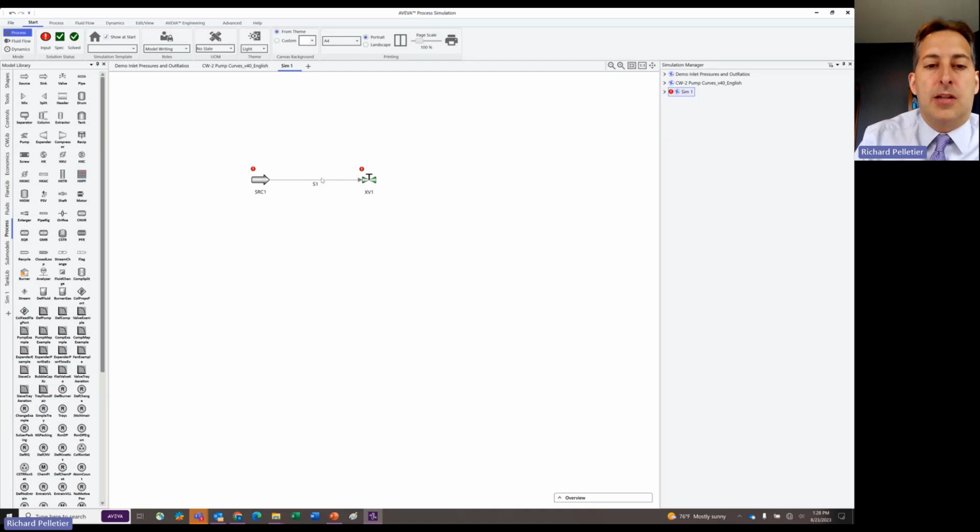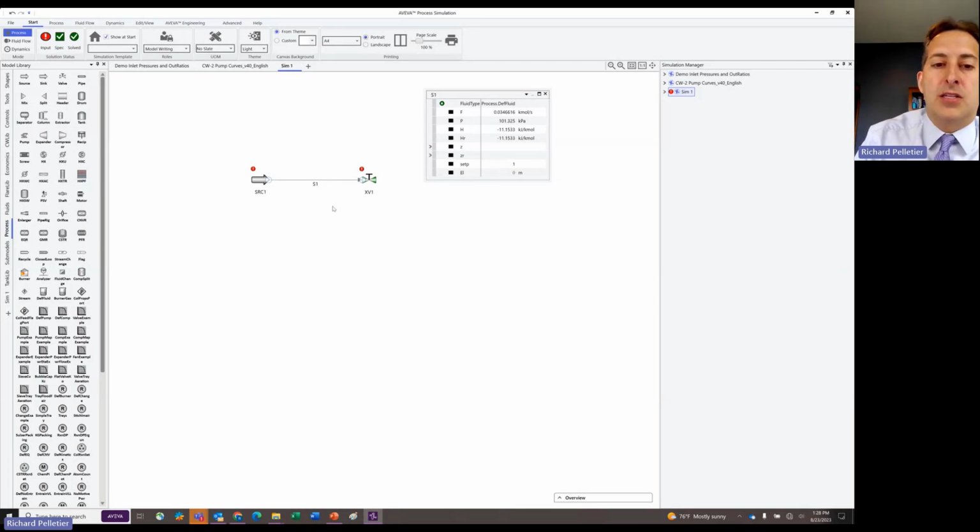And so I double click and I look at this, and I'm like, oh, wait a minute, there's no mass flow rate, there's no volume flow rate, there's no temperature, right? What are these properties that would normally be calculated in a stream, right? There's nothing being populated here, right? And the whole reason why is because normally that information is being populated through the stream connection model that's embedded on the link, right, on the connection.